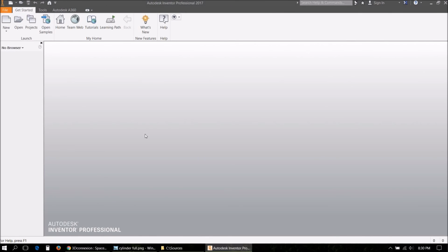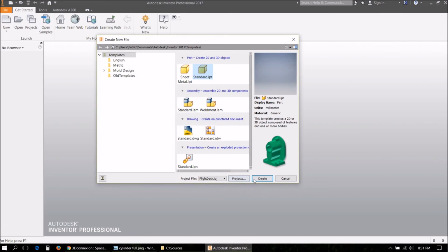So the first thing to keep in mind is that you want to create all your models using the same basic orientation. For example, all models have the default view being front on, or all models have the default view of being viewed from the top. Now, to help with this, it's best to create a ground plane. So you can't view that right now, but if you create a new part, then I can show you how that's being made visible.